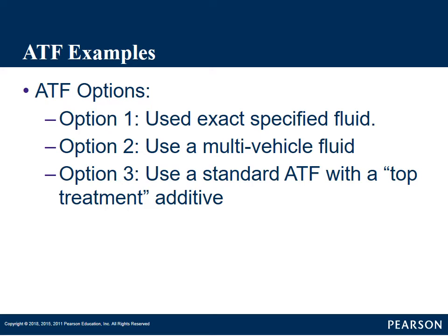I know in the early days of Chrysler, when they were still using hydraulically operated transmissions, when they were just switching to ATF+3 from Dextron, you could put the Dextron in, and a company called LubeGuard had an additive that you could put in with Dextron that would then meet the standards of ATF+3. Because what would happen if you used regular Dextron, the valves and the governor on these transmissions would stick.